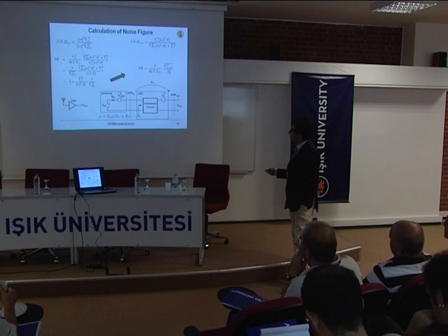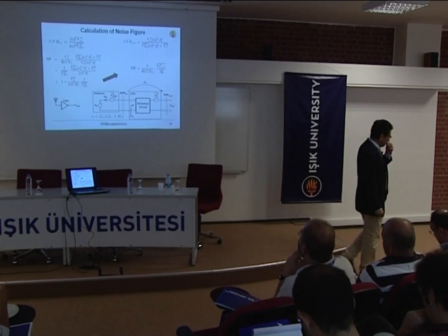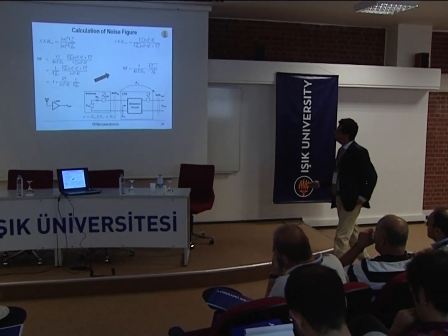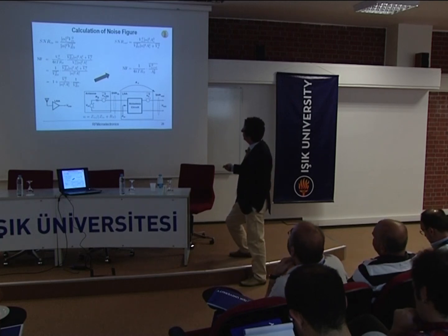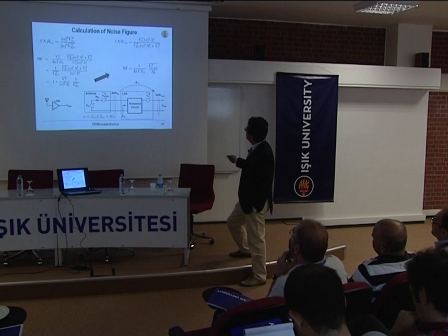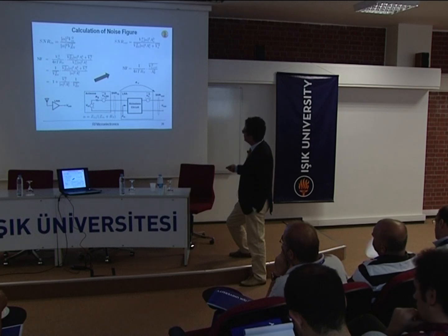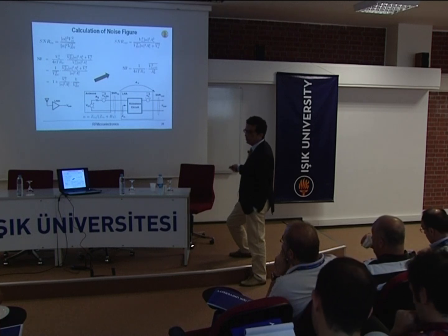So looked at in another way, once we know what is the output noise produced by a circuit, we call it Vn. And this will be the basis in the future calculation to determine the noise figure of any circuit. So again, we attribute all the noise of the circuit at the output through this voltage source V squared N. So we say the signal is Vin squared, alpha squared, AV squared, and the noise adds up, the noise over RS plus the noise of the circuit, okay?